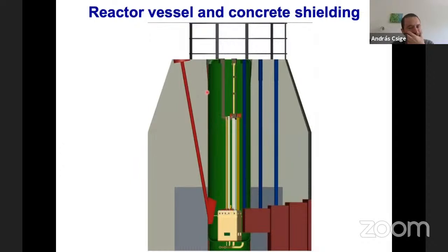Here you see the reactor tank with the core at the bottom. The upper part is open to the atmosphere. It also enables easy access to the core. Water level is up here, and experimental vertical channels can be accessed through ports here on this shelf, which is 1.5 meters below the water level. This is the shielding when removing irradiated samples through these ports.